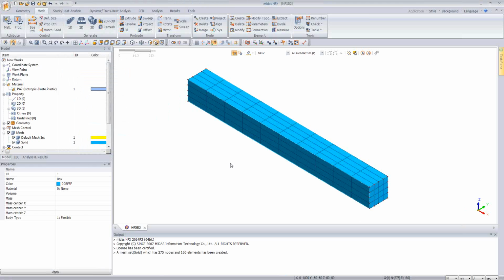Okay, so the mesh is done. And okay, so we have that, and right now we can add some additional element, because our purpose is to perform strain control simulation. We need to add some element which gives us a capability to control the strain, and one of these elements is the rod element, which has got the ability to